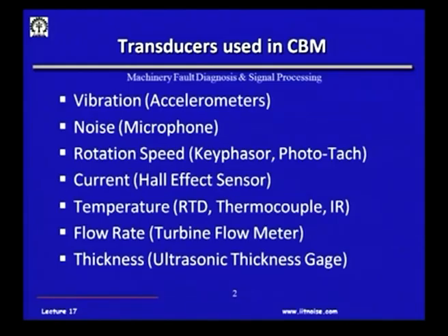So, such scale formation or deposits will reduce the internal thickness of the pipe. So, from outside, how do I know that such a buildup has occurred in the inner walls of the pipeline? This could be very easily measured online by an ultrasonic thickness gauge.